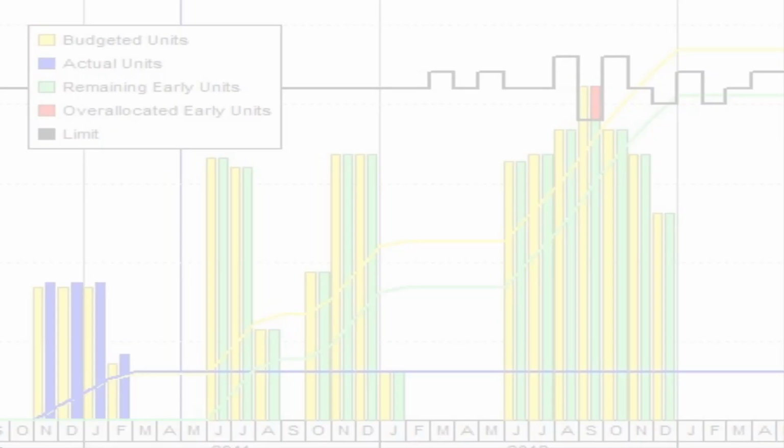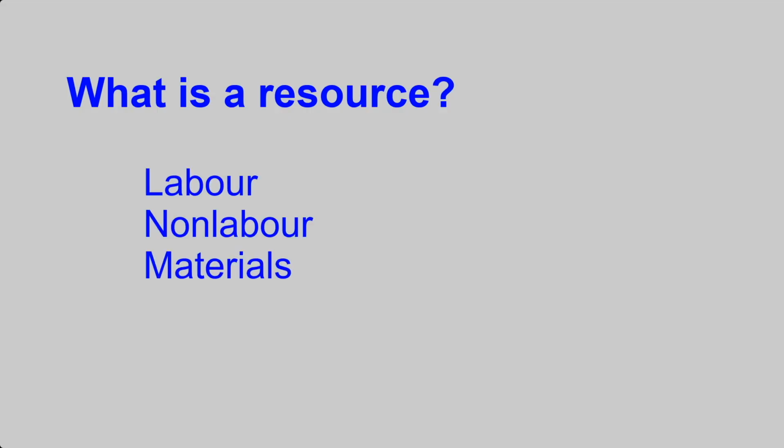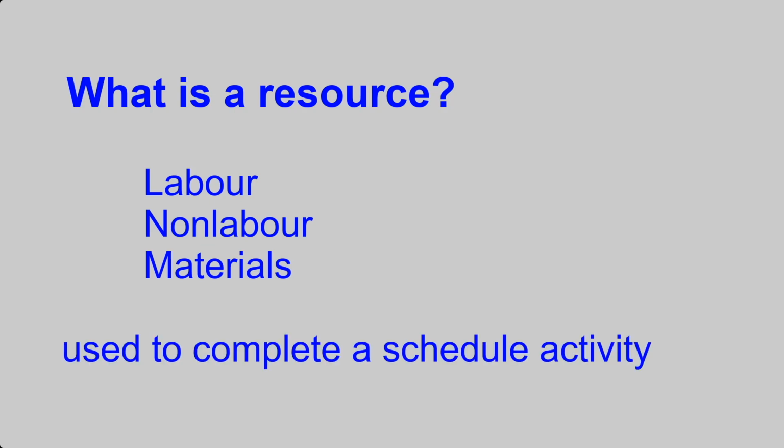In the last lesson, we learned how to import and export projects in P6. In this lesson, we will discuss how to create your resources in P6. So what is a resource? In P6, a resource is labor, non-labor, or materials used to complete a scheduled activity.